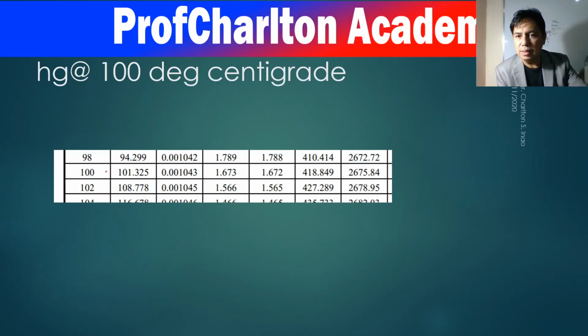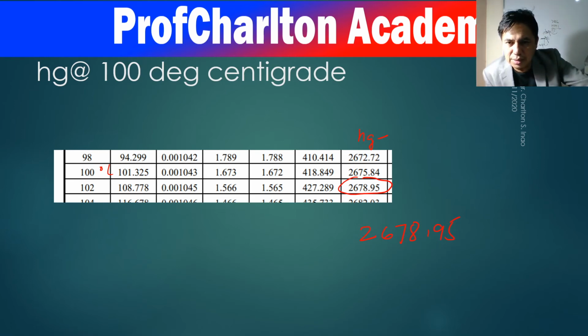So this one is 100 degrees centigrade, and this is the Hg, meaning enthalpy of gas at the saturation line of vapor. So here there is 2678.95. And what did I get? Because this one, I solved years ago.